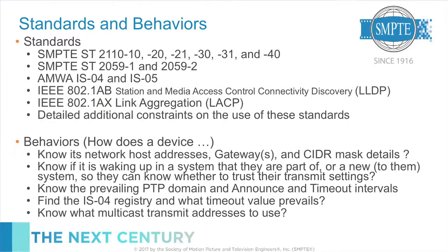And if a device isn't already doing it, it's because you forgot to turn it on. It's not that hard. Link aggregation. If you're going to have multiple connections to the control network, we specify that you'll use link aggregation because, you know, the control network is becoming really important. And that single connection to it is actually a single point of failure for devices now. So that's fine. Standards, we all understand standards.